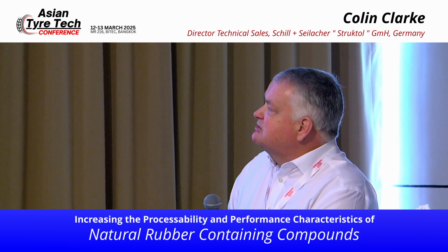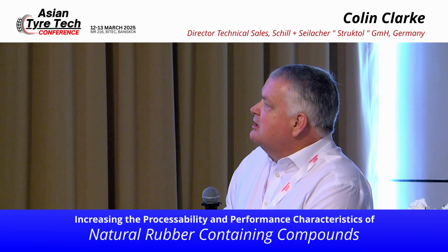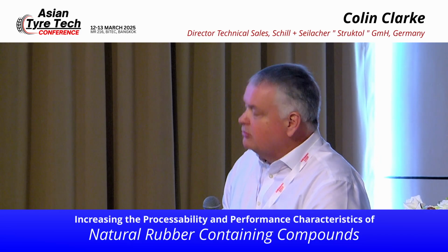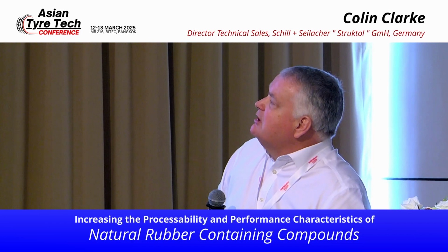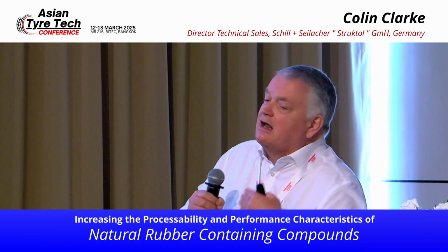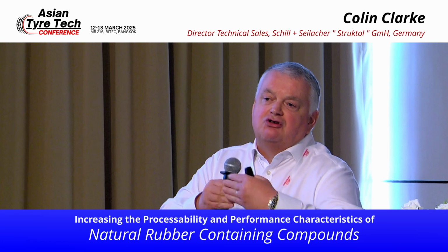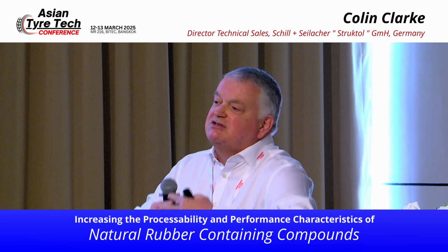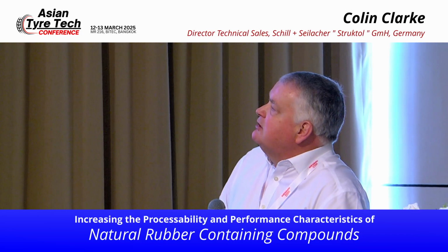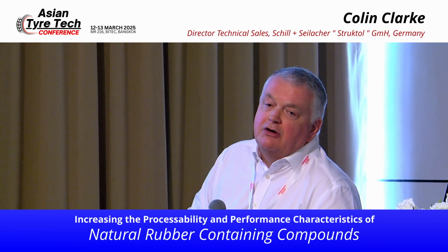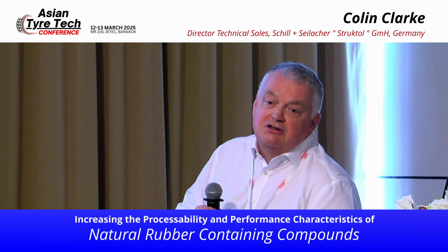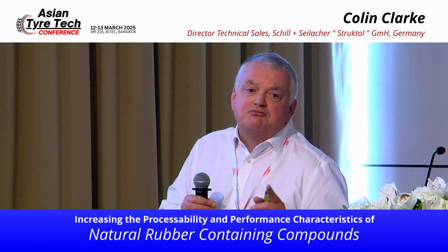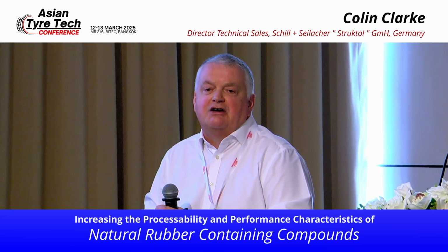By contrast, mechanical mastication, just the mixer itself, statistically, we break down preferentially the longer chains more than the shorter chains because longer chains are more entangled, and when we apply shear forces, stress forces, they break preferentially. So actually we reduce long chain material, but we don't increase the short chain material too much. This is good for dynamic properties. And actually our HT105 pretty much mimics what we had with mechanical mastication.